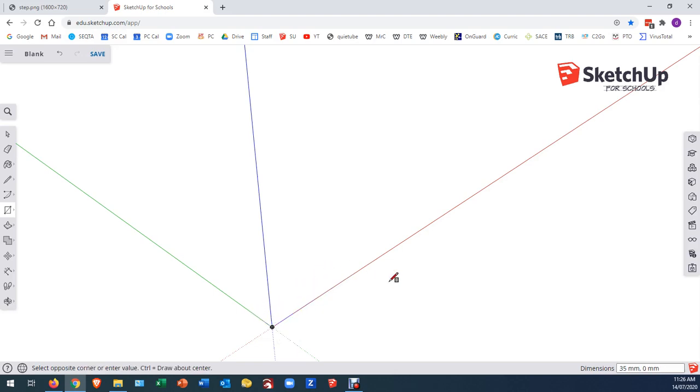out. Now as I drag, I'd like you to be looking at the dimensions block, because when I drag in this way, you can see firstly there are two numbers in the dimensions block, 47 millimeters, 7 millimeters, and that tells you that the length along the 47 is along the red, whereas if I come this way it switches around. I've got 8 and 79, so the 79 millimeters has been measured along the green, so that is the red dimension, the green dimension.